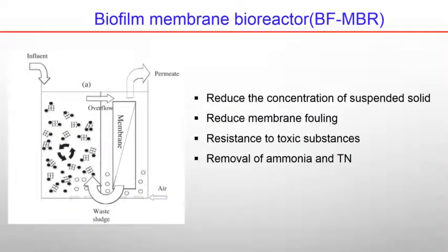Next is the biofilm membrane bioreactor. It is called BFMBR. BFMBR is the addition of carriers inside the MBR that reduce the concentration of suspended solids and lead to mitigation of membrane biofouling. It has a resistance to toxic substances. BFMBR showed a better removal of ammonia and TN.